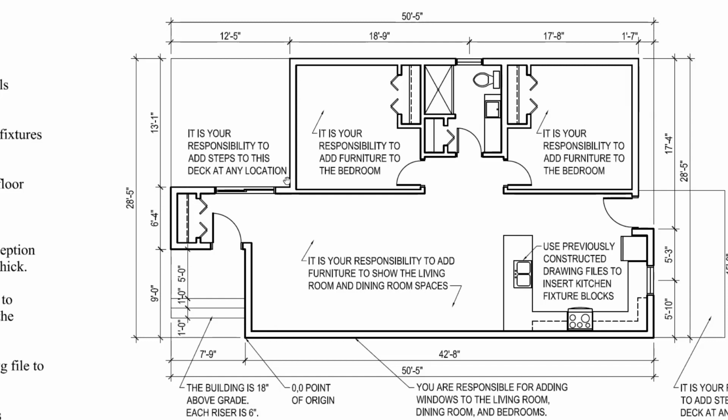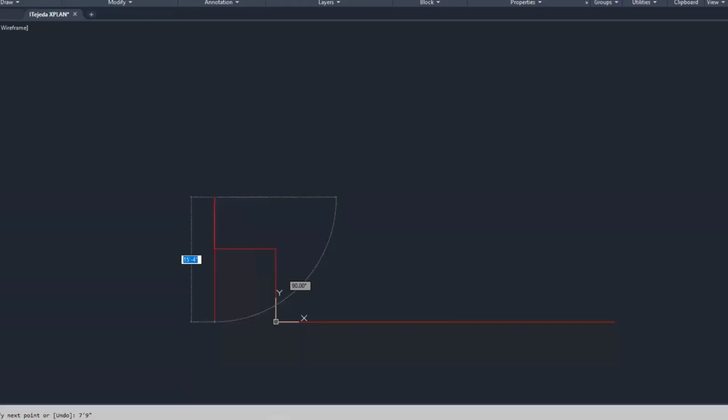And this distance here is 12 feet 5 inches. So I'll type that in. 12 feet 5. And you notice I've been typing the inches, just because I want you to get into the habit of knowing how to use feet and inches. But once you're comfortable with it, just know, this is a friendly reminder, that I don't have to type in inches. It's automatically understood that if I just enter a number there, it's going to default to inches. So 12 feet 5, and I enter.